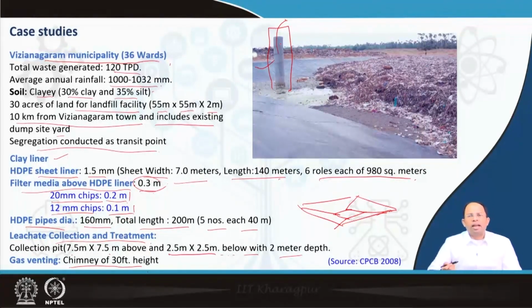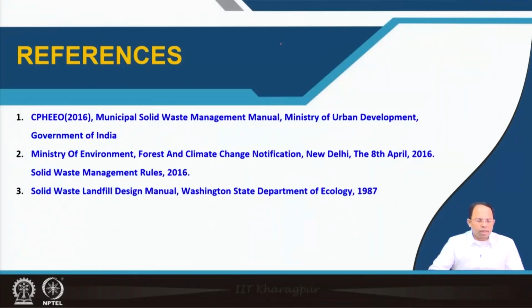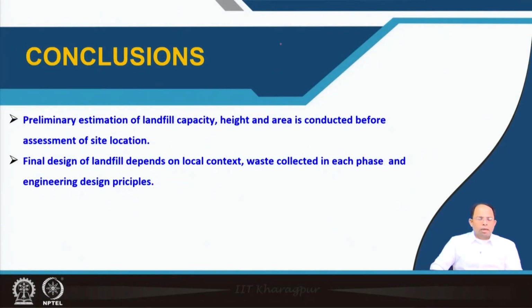Similarly, all landfills in future need to have, as we have discussed, gas management systems, active ones, leachate management systems, water management systems, surface and groundwater systems, and so on. These are some of the references you can study. To conclude, preliminary estimation of landfill capacity, height and area is conducted before assessment of site location. And the final design of the landfill depends on local context, waste collected in each phase and engineering design principles.